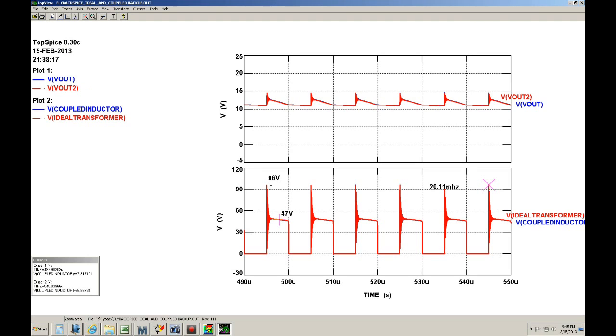So basically you're adding quite a bit of voltage over this, and this ringing is also causing heat to be generated in your MOSFET. Okay, so those are two things. And the third is that you're creating EMI that could be conducted back to the bus or radiated.